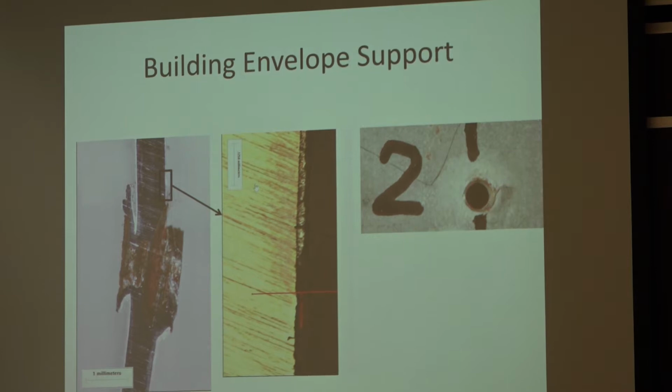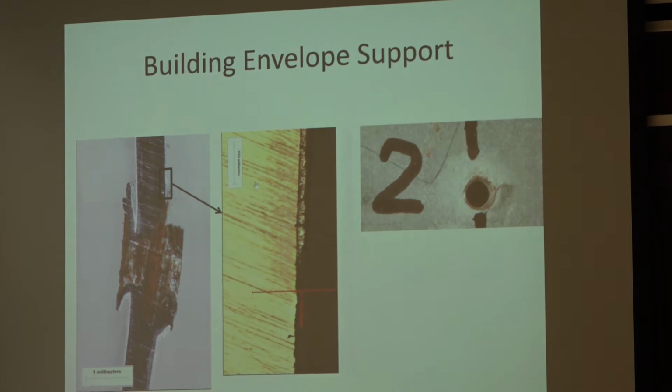And that's the threat as far as this specific application, where, say, after 3 years, you've essentially exhausted the galvanizing that can protect this threaded area, and from there on, you're going to be susceptible to corrosion. So you have to do something. You're not going to last the original 50-year design.